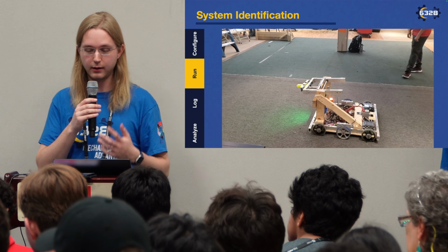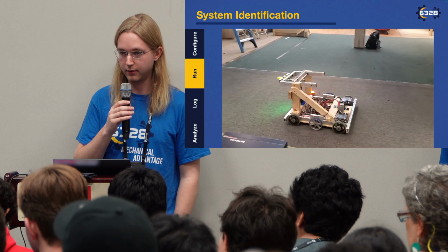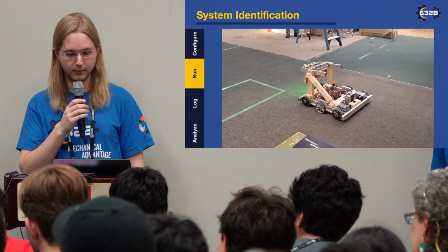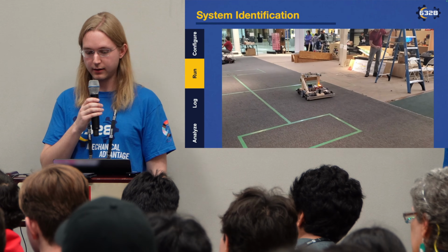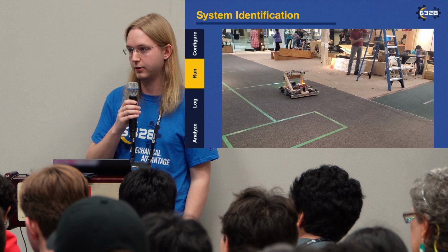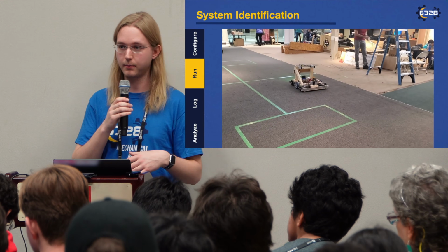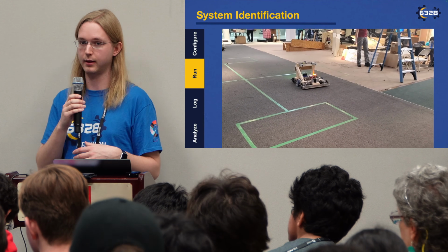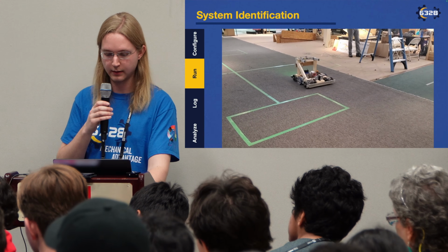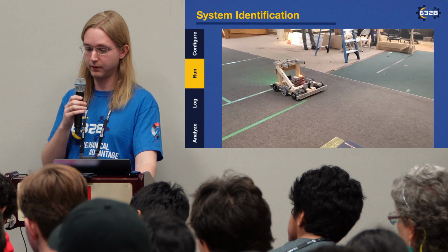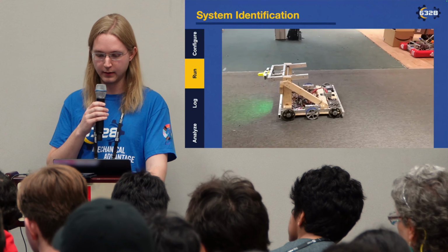So now we just run these 4 tests in Autonomous. These are measuring how the voltage affects the velocity and acceleration of the drivetrain in this case. So what you're seeing here is a quasi-static test. This is measuring how the voltage affects the velocity by slowly ramping it up. We do that forward and backward, followed by a dynamic test that measures how the robot accelerates when running at a constant voltage. This is applicable to all kinds of other mechanisms, including swerve and flywheels and arms, etc.